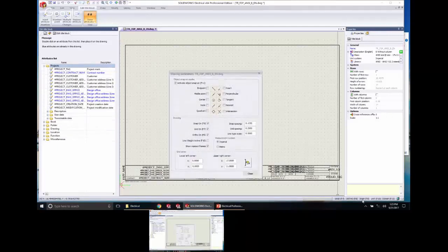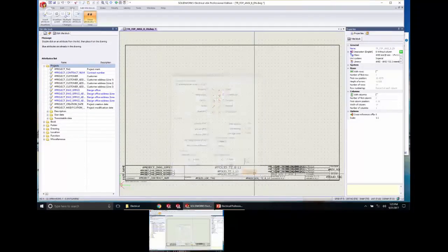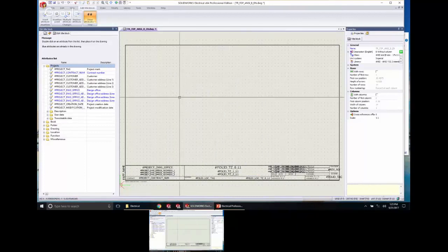You can always right click on this and it brings up an extended menu. And of course, snap, where you can have things snap to a part of your geometry. Okay. So here's where you would adjust your snap spacing, your grid spacing, all that stuff. You can set your grid zone, change your measurement system, all from here. Okay. And again, that's just a right click down here. All right.